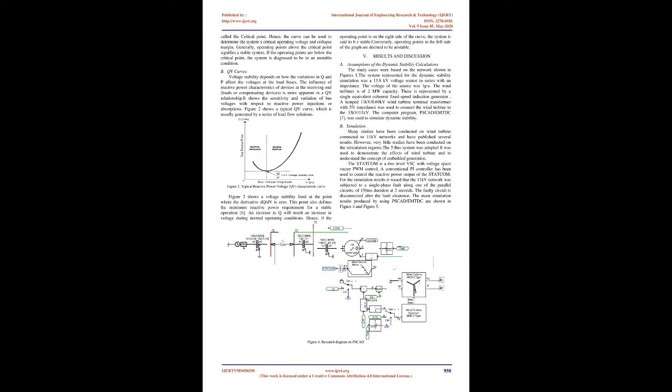4. Voltage stability. A system experiences a state of voltage instability when there is a progressive or uncontrollable drop in voltage magnitude after a disturbance, increase in load demand, or change in operating condition. The main factor which causes these unacceptable voltage profiles is the inability of the distribution system to meet the demand for reactive power.